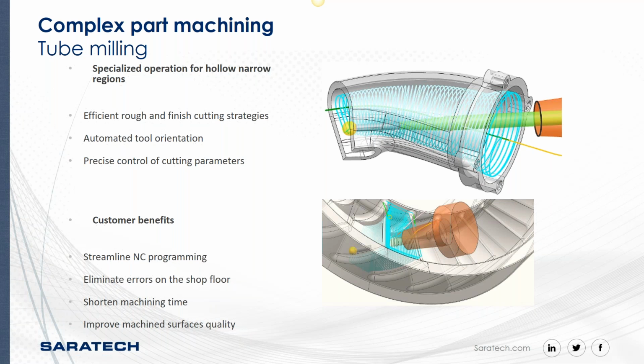Some of these operations here are very complex, and they give us toolpath that traditionally would take 20 to 30 different operations to get the same type of toolpath. The tube milling is specialized. It's been built for things like manifolds, and even manifolds that have the air disturbance nodules inside that break up the airflow. This operation easily configures and performs to cut that. And we have different options to go from one side or from both sides if your machine tool is capable. It will produce toolpath for ball mills, but it's very uniquely specialized for spherical mills.